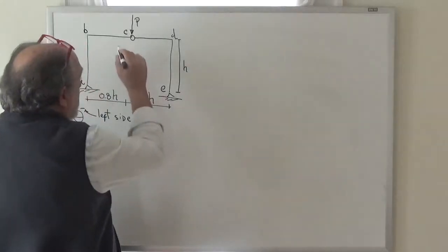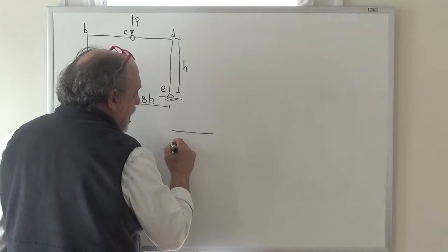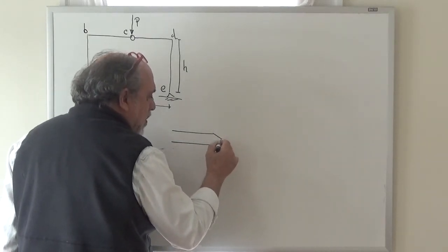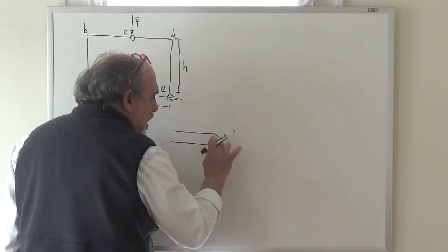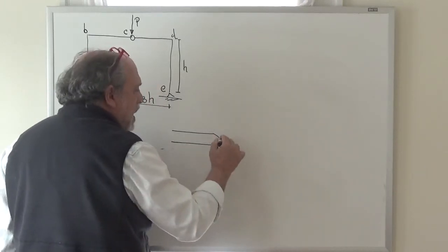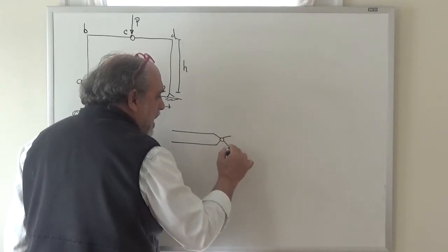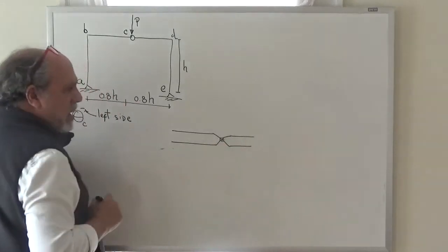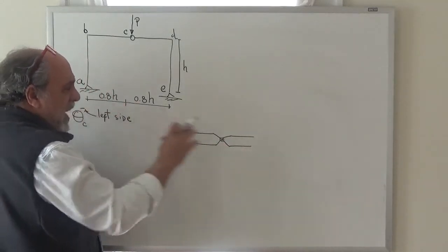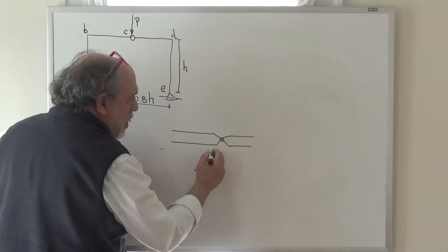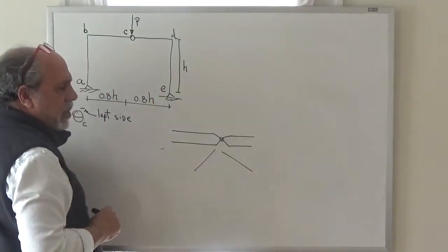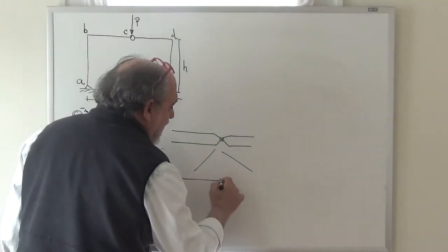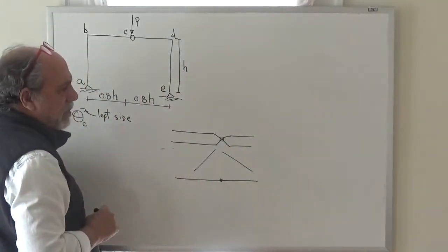For example, this beam could be a thing like this, and then at point B there could be a tapering, and then a circle here like that, and then there could be a thing like this, and a thing like that, and that could be C, and then there's a bolt that goes through it, or whatever you'd like, right? So that is really a hinge, in the sense that these two bars can rotate relative to each other at the hinge. For mathematical purposes, of course, we are idealizing that as a point, like this, right?